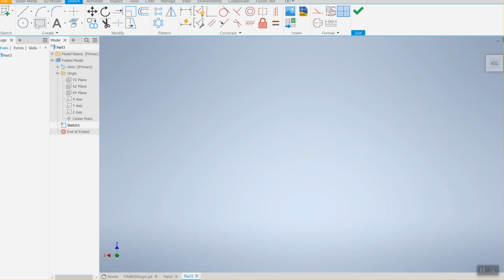We are starting with the rectangle. This is one of the side walls. So after clicking on the rectangle, move your cursor over the reference point, the 0, comma 0 point, and click to start. After you pick the first point of the rectangle, the computer will give you the option of typing the length. And I'm going to type.